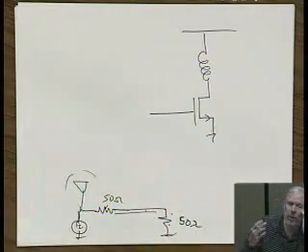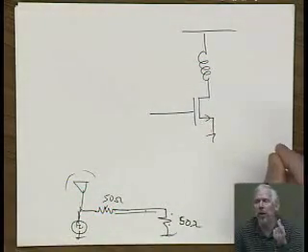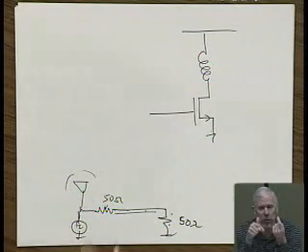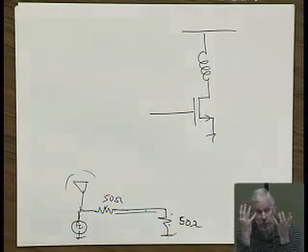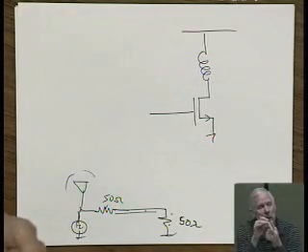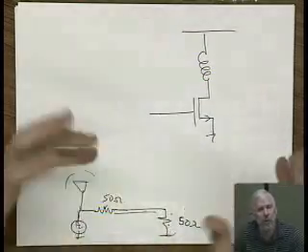We're not going to talk about transmission lines, which is a different bit of RF stuff. But that's not relevant on a chip because the distances are so short, you're not looking at transmission line effects until you go to very, very high frequency, like 60 gigahertz. Then you look at transmission lines on chip. But until you get up there, it's not important. So this 50 ohm thing is a little bit of a carryover from the old days.